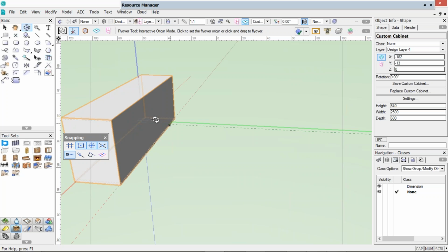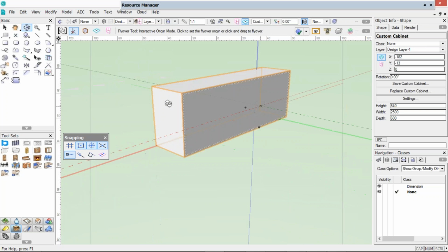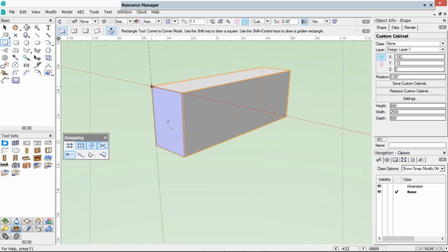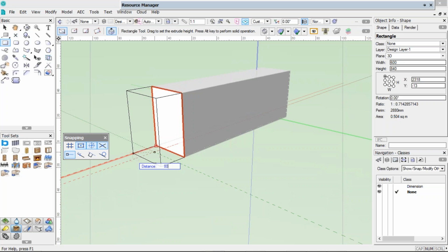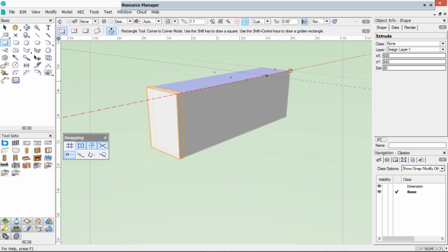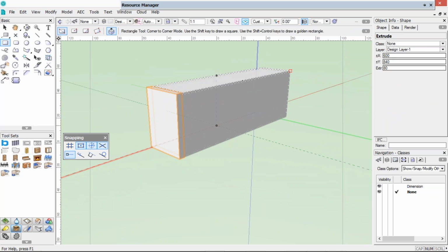So one of the easy ways I felt to draw that island unit was to put the cabinets in first and then use my automatic working planes, draw a rectangle, and extrude that, and I extruded these by 80 millimeters, which is just over 3 inches. And then you can mirror it to the other end, because if you can find the middle cabinet, you can easily mirror that.